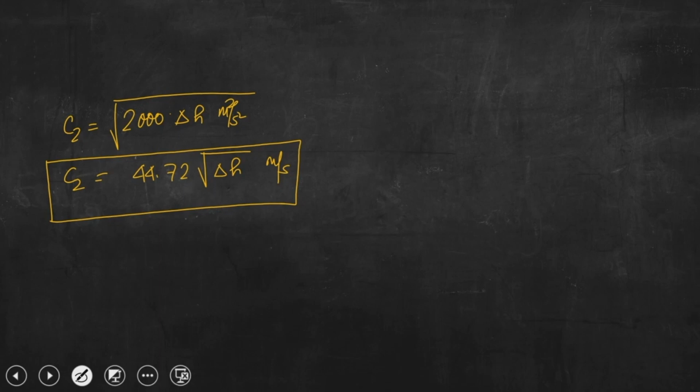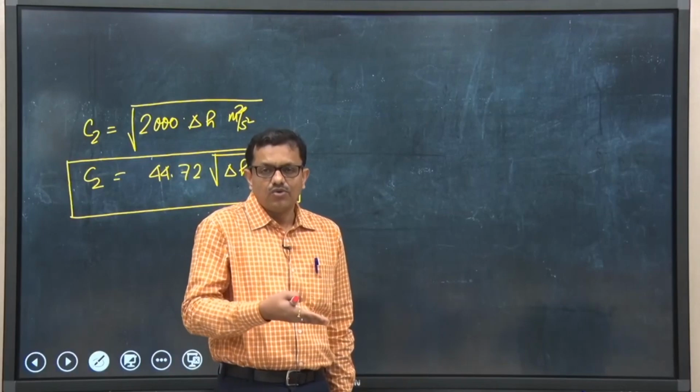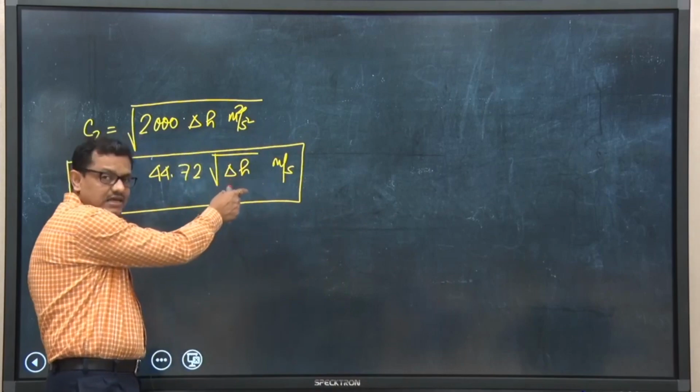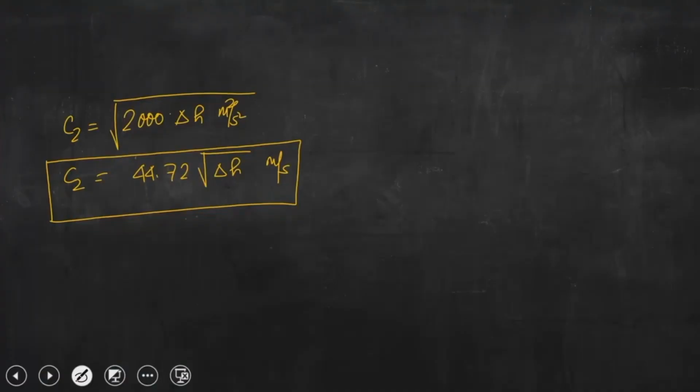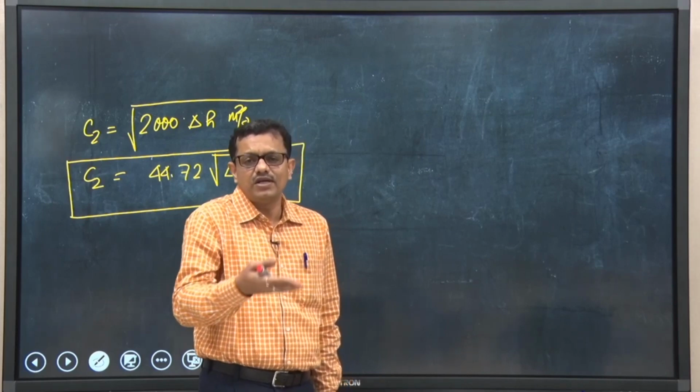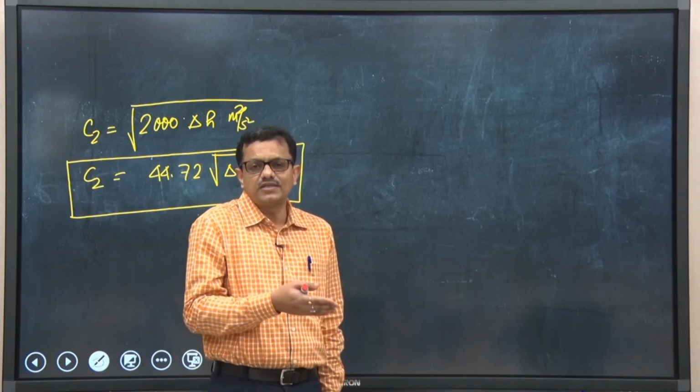What would be the enthalpy is very important to know, and since the enthalpy drop should not be delta H, that is why the nozzle will also have some efficiency. Ideally we are thinking, okay fine, if the enthalpy of steam at the inlet is H1 and the enthalpy at the exit should be H2, that would be obtained from any Mollier diagram, because the process is isentropic.